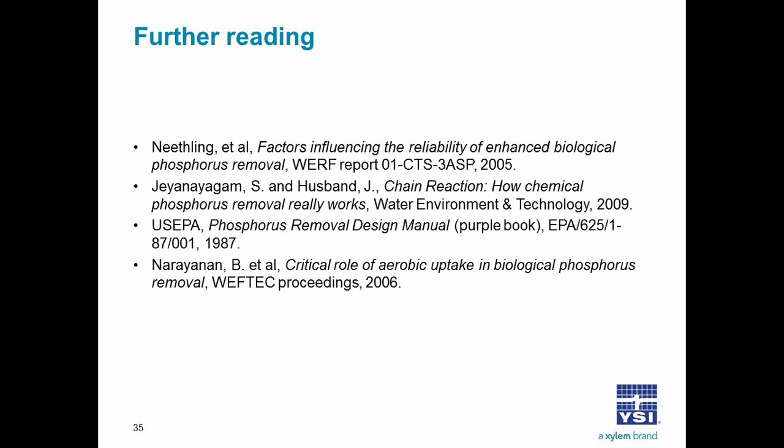But in general, the values indicating biological phosphorus release are negative 100 to negative 250 millivolts. This could be more or less for your facility. As far as uptake goes, certainly it needs to be in the positive range, so plus 25 and higher.